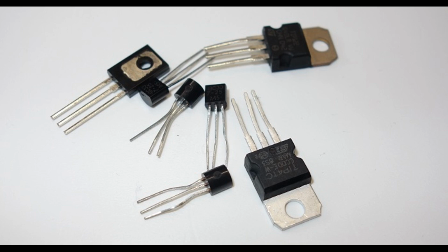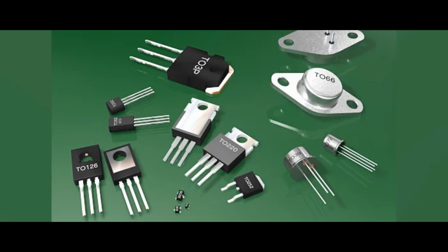JFETs are formed by creating a PN junction between 2 differently doped regions in a semiconductor material. The 2 common configurations of JFETs are N-channel and P-channel. In an N-channel JFET, an electric field created by a voltage applied between the gate and the source controls the flow of electrons through a narrow channel. Similarly, in a P-channel JFET, the electric field controls the flow of holes. JFETs are typically used in low-power applications and as voltage-controlled resistors.